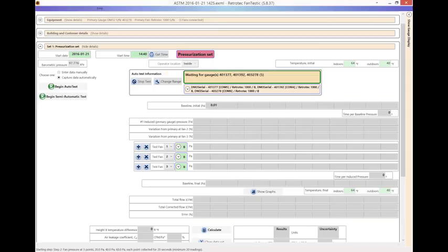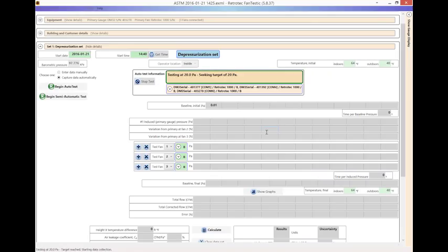And so what it's going to do right now, you may hear the fans in the background. I apologize for the noise, but I have 3 fans in the room. They're basically duct testers that I've converted to act like a blower door so that they don't get too loud and they all fit in my office. So they're all set to the B range. And now they're going to establish the first test pressure, which is 20 pascals.